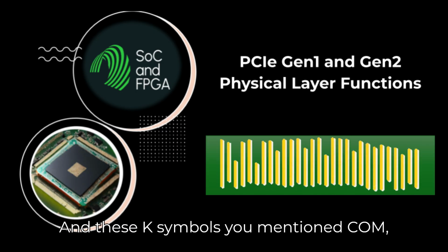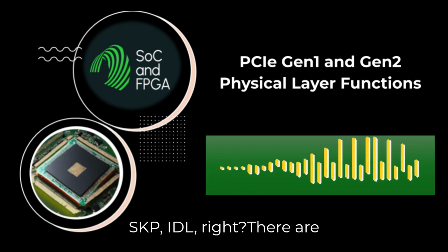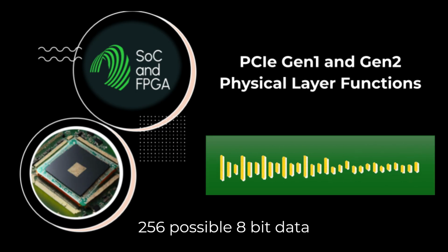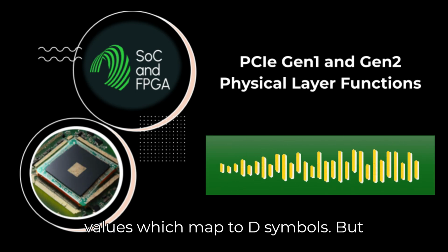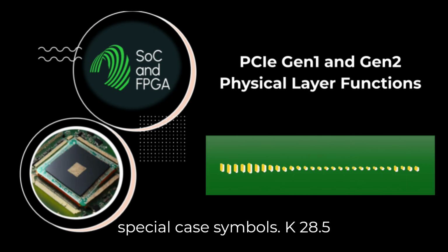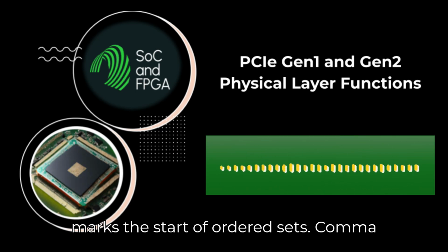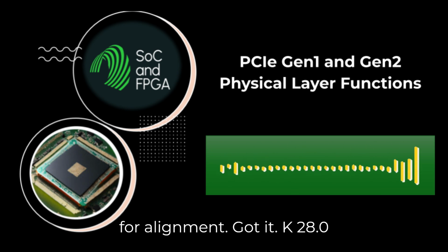Fascinating. And these K symbols, you mentioned COM, SKP, IDL. Right. There are 256 possible 8-bit data values, which map to D symbols. But the encoding scheme also defines 12 special K symbols. K28.5, COM, is crucial for symbol alignment and marks the start of ordered sets. Comma for alignment. Got it.